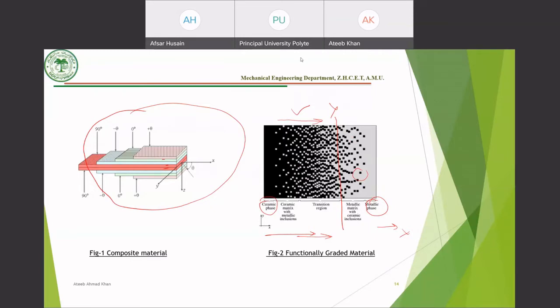You're welcome. Sir, regarding the concrete also, I want to add some supplementary answer. You don't mistake me. Even though concrete is a mixture of three or four different materials, at the time of mixing, after it becomes hardened, it is considered as a single solid, like a homogeneous material. Based on this concept only, the design of RCC or plain concrete is evolved. So it cannot be heterogeneous, or it cannot be called a composite material. Then RCC is called a composite material, since it consists of two different materials: one is a compressive material, another one is a tensile material.